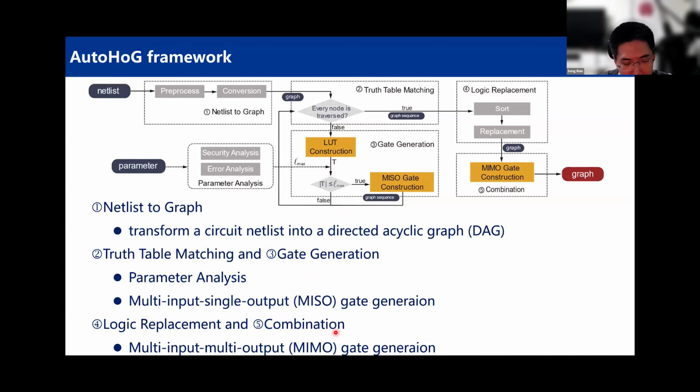And lastly, this is a recent paper, 22 or 23, I forget. What we have seen is that if you evaluate different functions, for example AND gates, OR gates, and XOR gates, where all the inputs for these gates are the same, then we can use multi-input and multi-output gates to further reduce the number of TFHE bootstrapping operations we have to execute over the circuit.